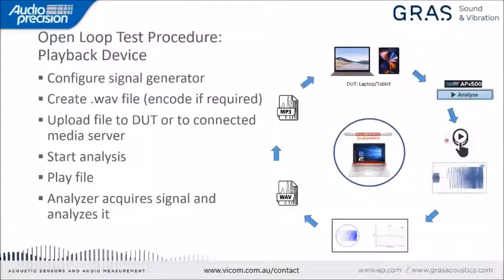So when we play the signal from the device under test, the APx analyzer will wait until it hears the pilot tone. And when it hears the pilot tone, it will trigger the signal acquisition. Once we acquire the signal, then we can analyze it.